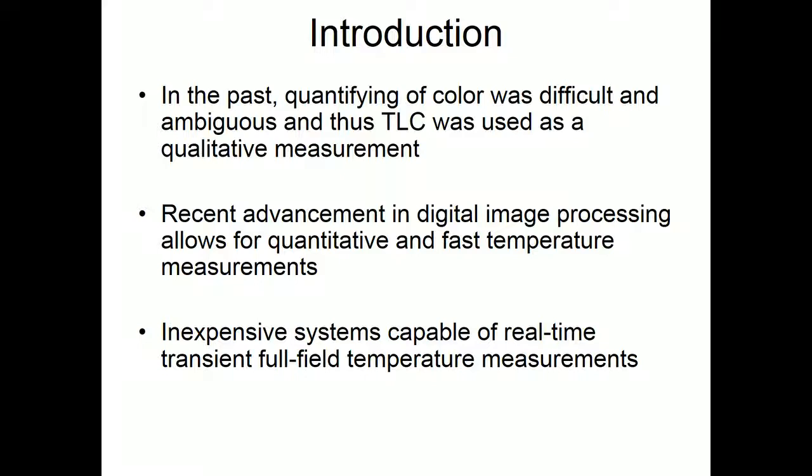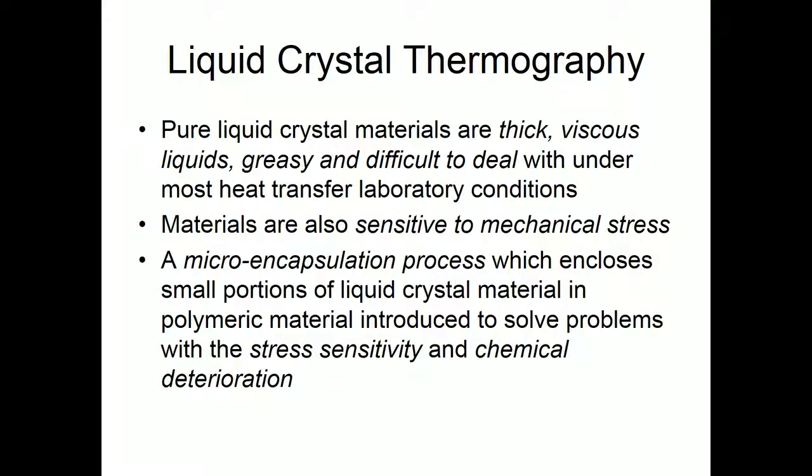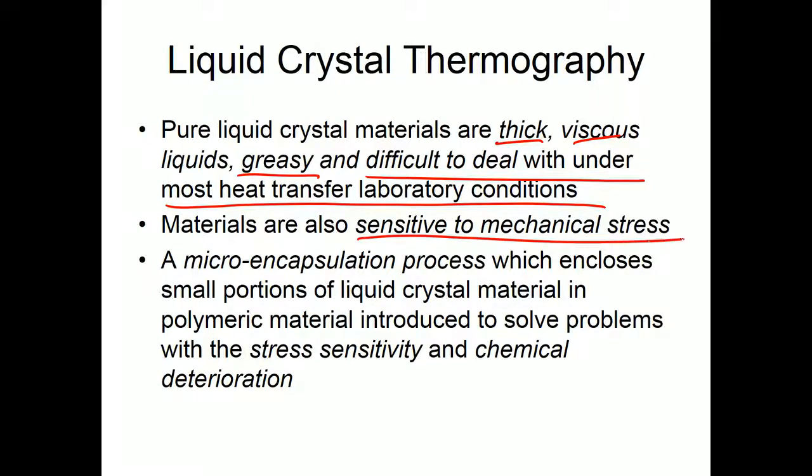Basically, all you need is a very high quality RGB camera, and the TLC crystals and the TLC sheet, that is it. Pure liquid crystal materials are thick, viscous, greasy, and very difficult to deal with under most heat transfer conditions. These materials are also sensitive to mechanical stress. Micro encapsulation is a procedure by which it encloses small portions of the liquid crystal material in a polymeric shell. It actually solves the problem of stress sensitivity and chemical deterioration.